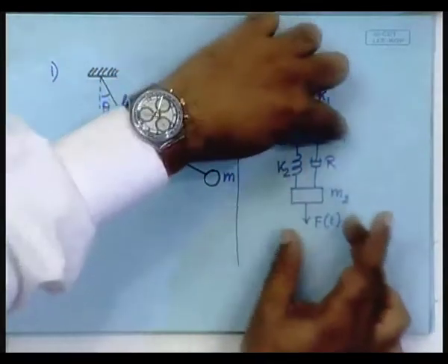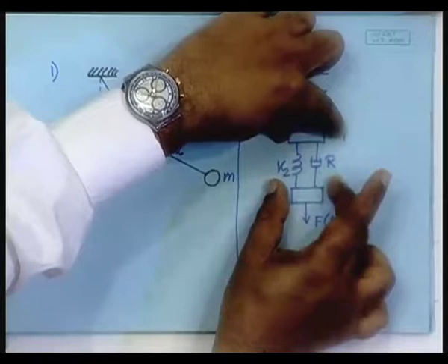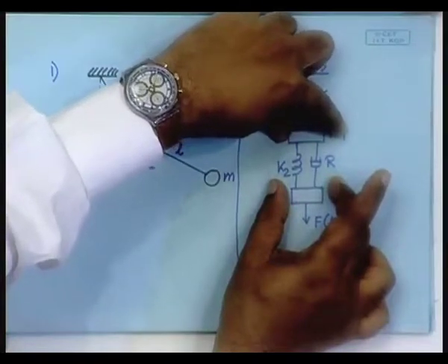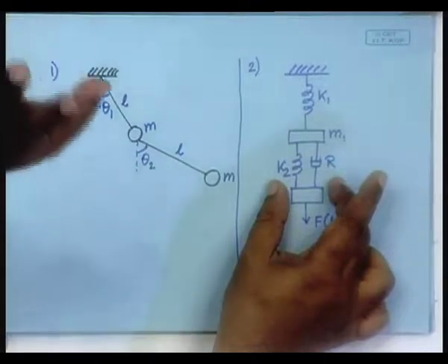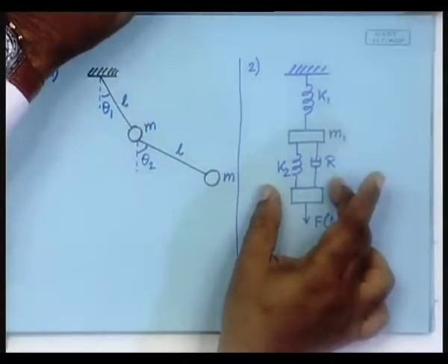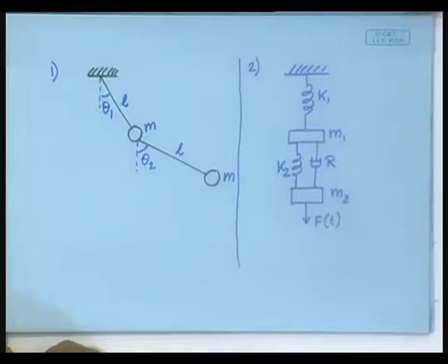Hold it there, and now raise this one, so that this one also goes to the unstretched position. Call these two positions of the masses the 0 position of Q1 and Q2, and measure from there. Both these possibilities are there, and you define according to what you find convenient. Both are equivalent actually. In one you will have one additional term which will cancel off when you differentiate.